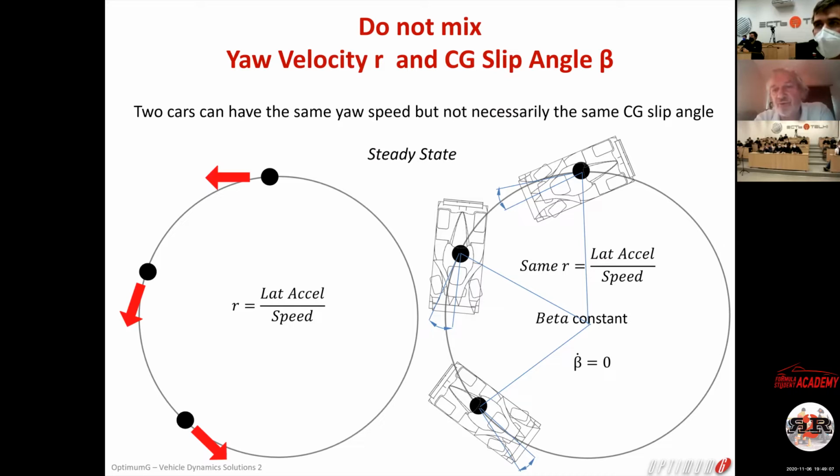And I asked them, what's the yaw velocity of the car on the skid pad? And the guys are looking at me and they say, we don't know. I said, come on, guys, what is your lap time on the skid pad? 6 seconds. 6 seconds, it's a bad car, because now you should be in the 5-second region. But let's say 6 seconds, okay? How many degrees is there in one circle? 360. 360 in 6 seconds, that's 60 degrees per second.